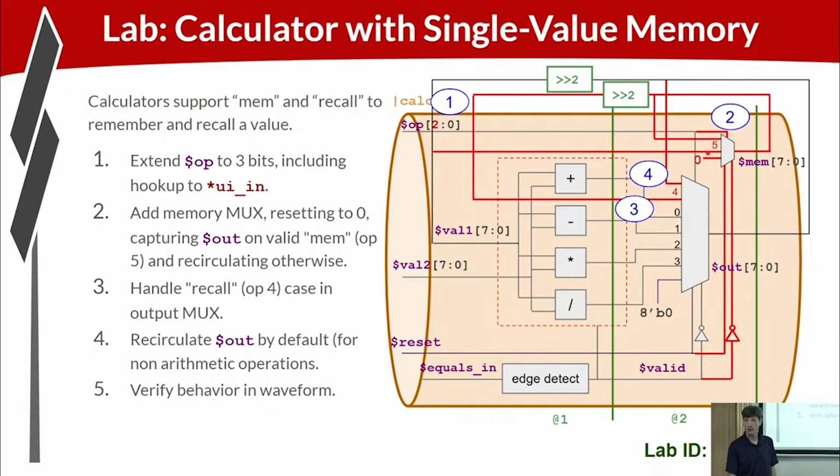Okay, so that memory is state. All our state structures have this similar structure. They're a multiplexer with a recirculation path to hold on to the value, and then other paths for update, right? And they're going to need a reset state. So this 0 input here and the connection with, where's reset? Reset is giving us a reset to 0.